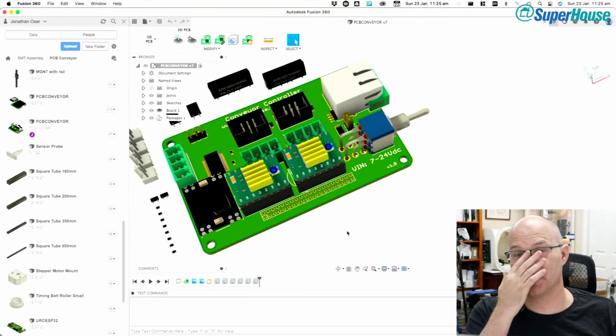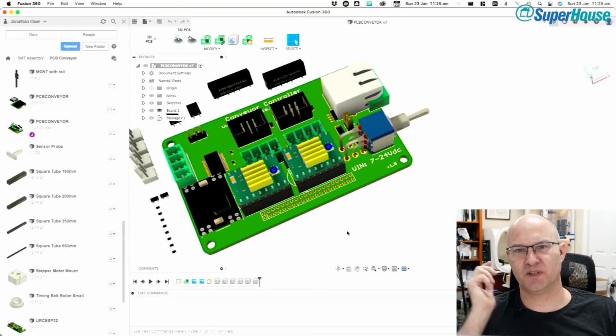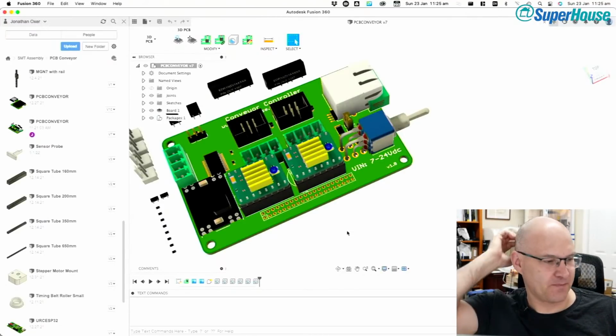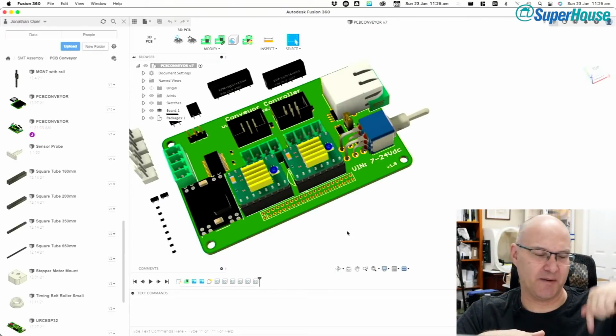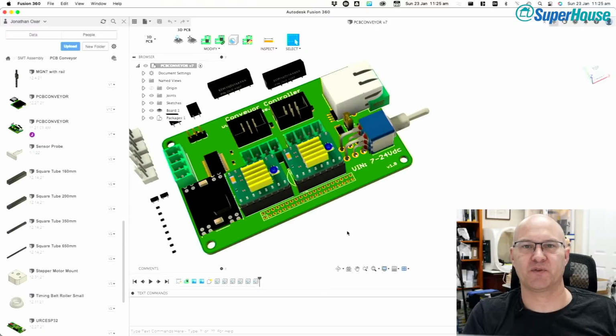Many boards are designed for a 3-axis system, say 3-axis plus extruder and heated bed, so a power output control and some temperature sensors and an input for a filament sensor. As a package for running a 3D printer, that's fantastic, but it is massive overkill if you basically just want to drive a single axis with a limit sensor and that's it.